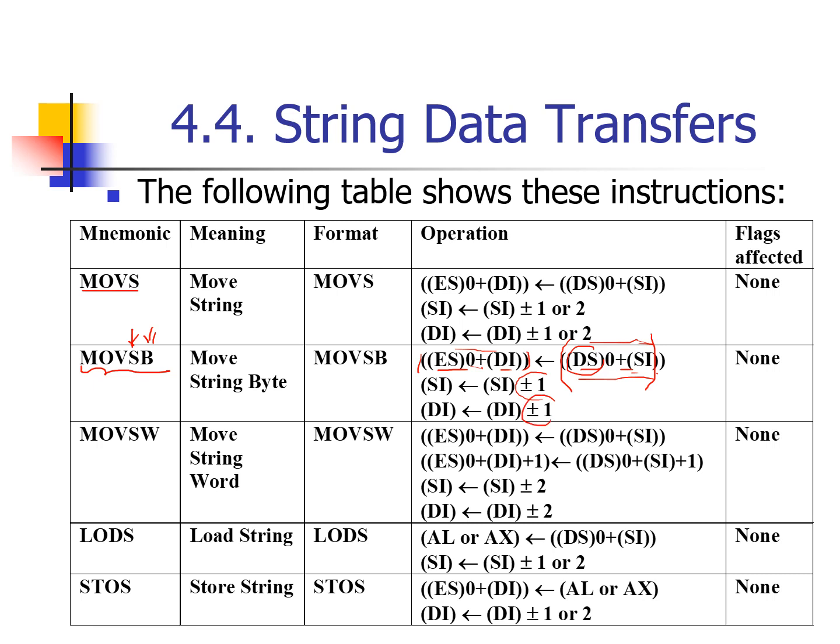And since you've chosen to write MOVSB, you are moving byte by byte. So you have to add one more byte forward, or subtract one more byte if you're moving backward. But if you are moving your data word by word, you have to add or subtract 2, because you're taking 2 bytes at a time.